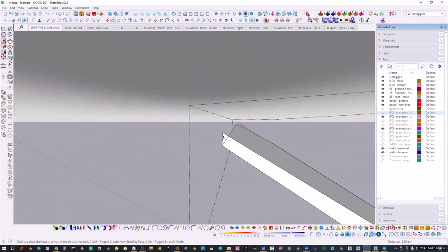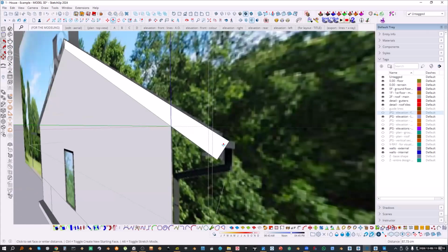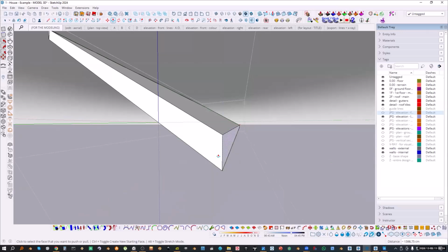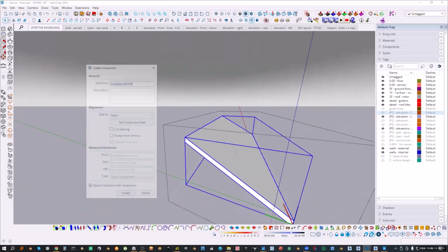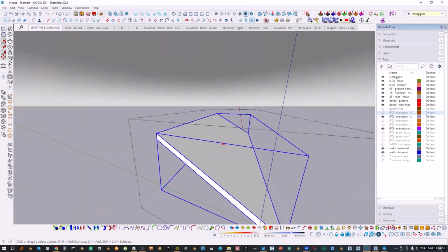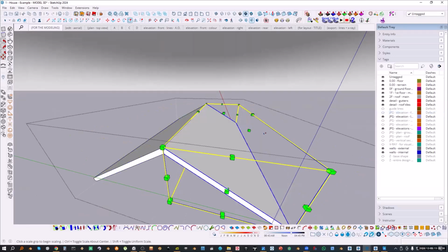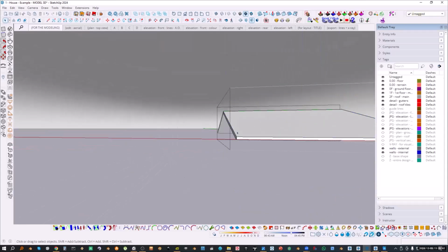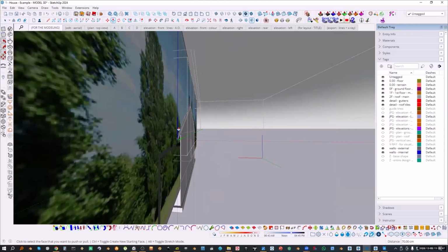All right. So I'm going to quickly block that out like this. Here with push-pull, I'm going to cut that. This as well. Again, fix it. And now I'm going to make the component from that. Control-C, copy the original position, minus 1 on scale, Shift-V, paste in place. And almost done. We just need to stretch that like 70 centimeters further and 70 here.